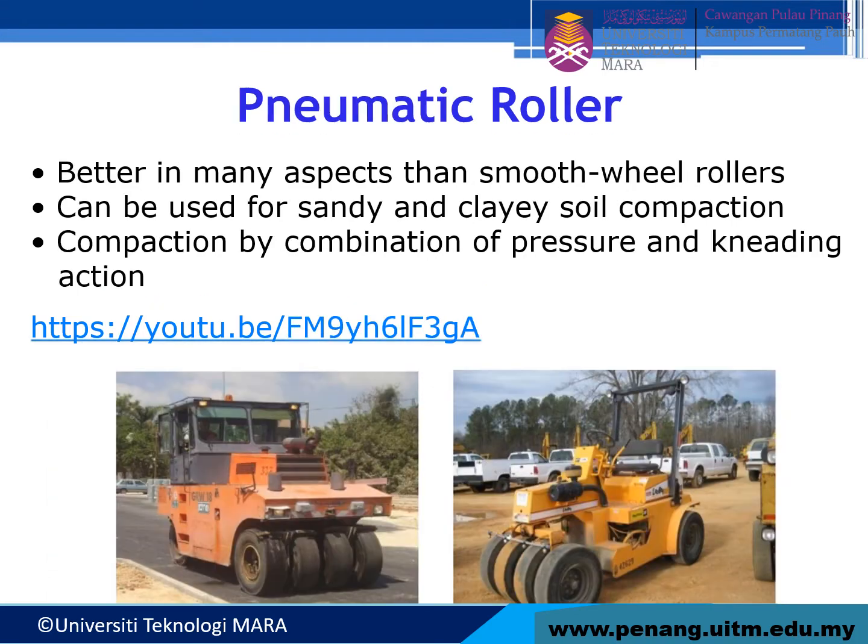Alright, pneumatic rollers. This one is better compared to the smooth wheel roller. Can be used for sandy or clay soil compaction. Compaction by a combination of pressure and kneading action. So this is way better than the smooth wheel roller. You may look at this picture here, and refer to this link for further information.